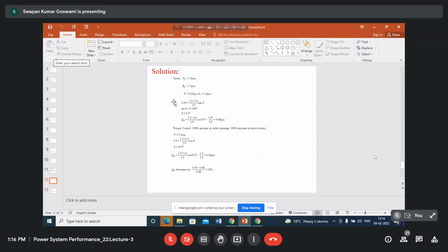The decoupling principle that we say in case of power system is re-established here: active power and delta are very strongly coupled. Active power and voltage are very weakly coupled. Voltage and reactive power are very strongly coupled.